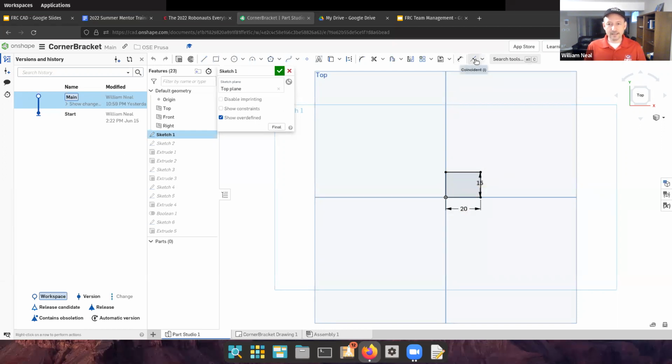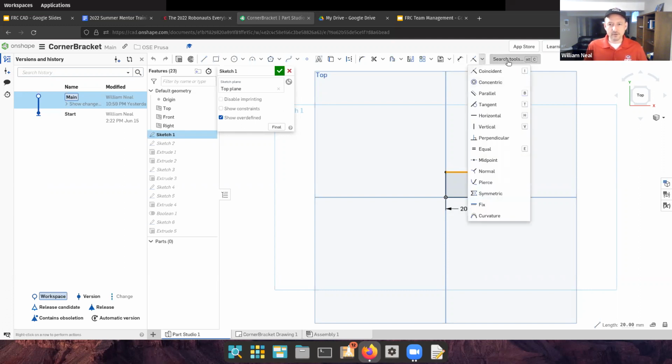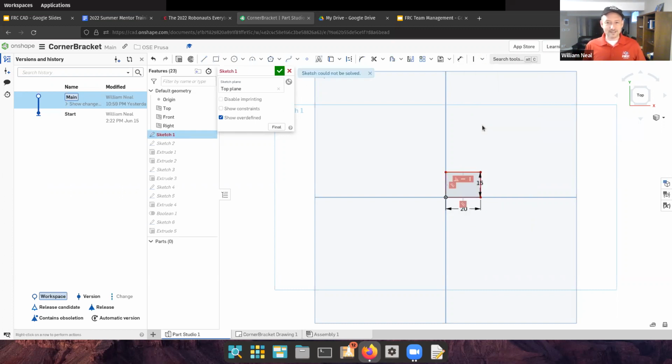So I applied these constraints much like this. I click a line there. It's now selected with my left button, and then I can actually specify something about it. I can insist that it be horizontal or vertical using this button. I'm not going to do that at the moment. Wonder what would happen if I try that. You see, it's issuing a contradiction because it already had assumed that one of the other lines was a different angle. So that produces a contradiction, and you see there are some error marks here.